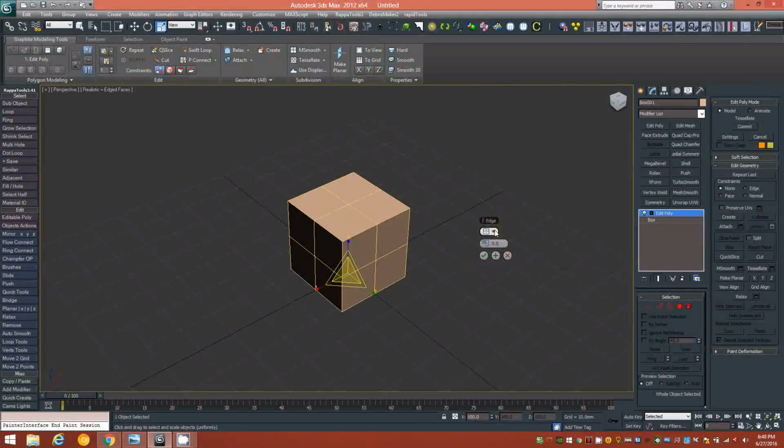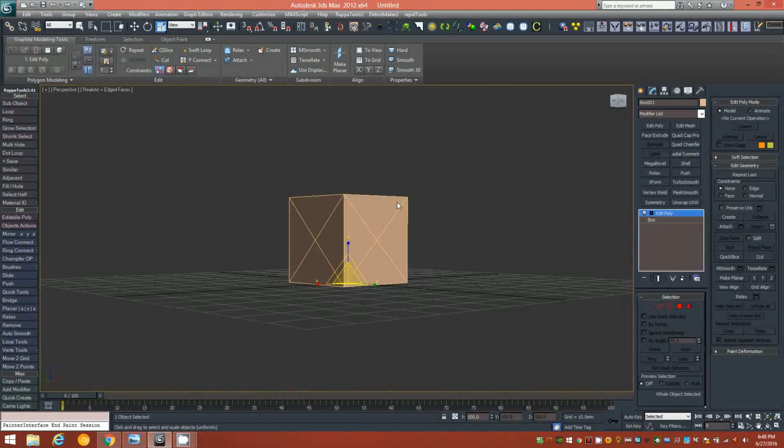We'll give it a tessellation, not with edge, but with polygon style tessellation. That'll create these X's along each of the planar faces of the cube. Just click OK. That's the pattern we want.